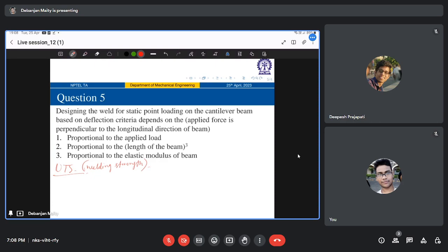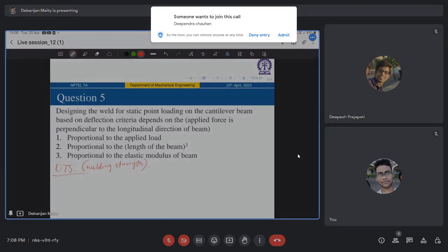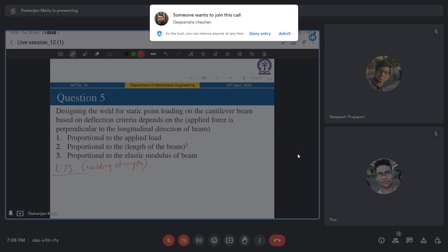Whenever the yield point is reached, some small yielding will happen there, and after slight yielding the maximum stresses will be transferred to another point of the weld, because of the straining. At the other point where stress concentration is achieved, the stress value will be more than the limit.